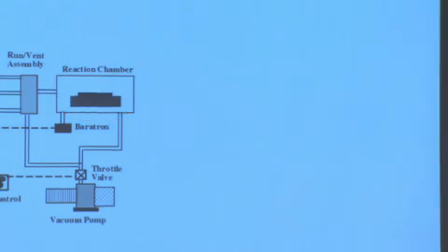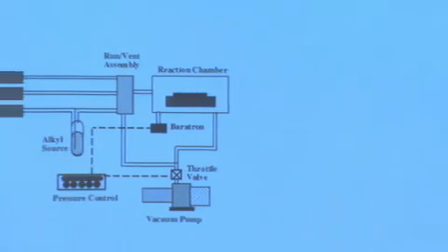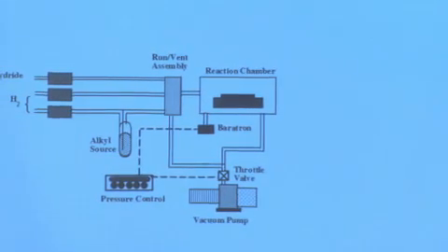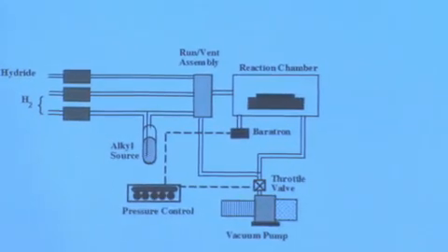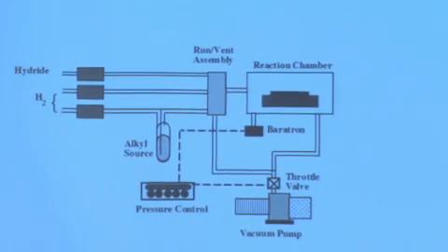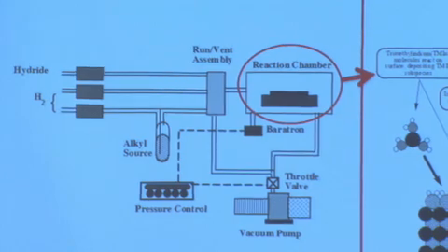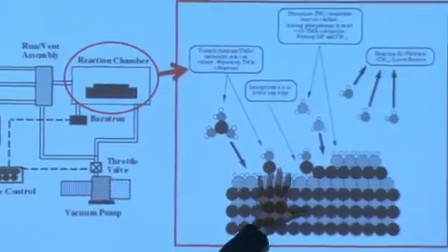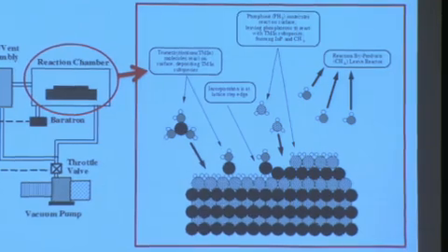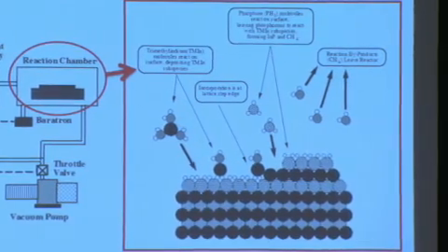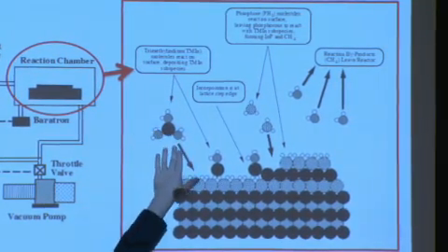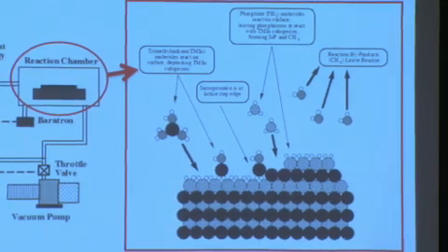And what we do is we flow these molecules into our reaction chamber and control the temperature gradients inside in such a way as to have those molecules deposit on the surface, leaving the indium behind, or the metal behind, and the reaction products float away out the back. That is represented chemically here on the surface. This is zooming in right at the surface of our sample, so right where the gas interacts with the thin film material that you're depositing. This is representing the incoming metal organic molecule, right, reaching the surface.